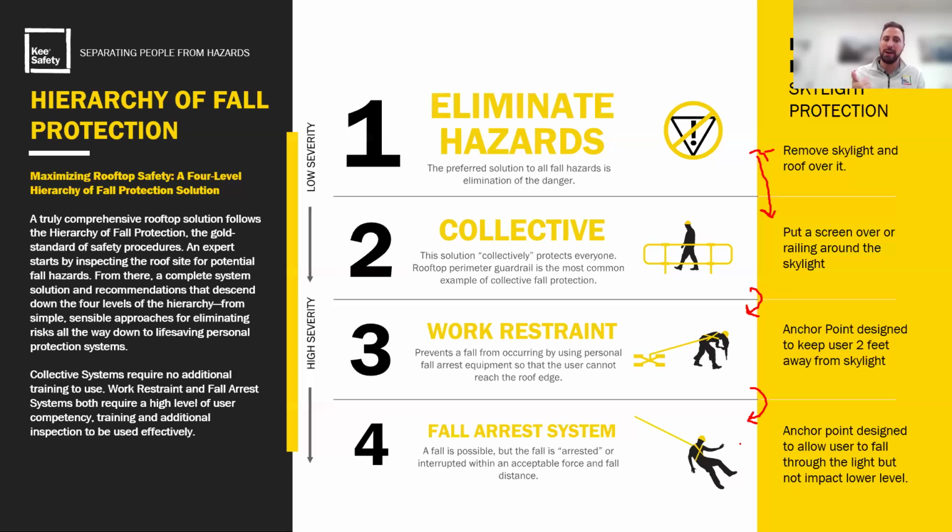So they've probably gotten whiplash from the fall. They've hit the side of the building. They may be knocked out, and they have a huge amount of pressure on their legs where their major arteries are coming in. So you have to have a rescue plan to get them down in less than 15 minutes, or we're going to have suspension trauma. So we have a whole set of issues when I have a fall arrest system that I need to consider.